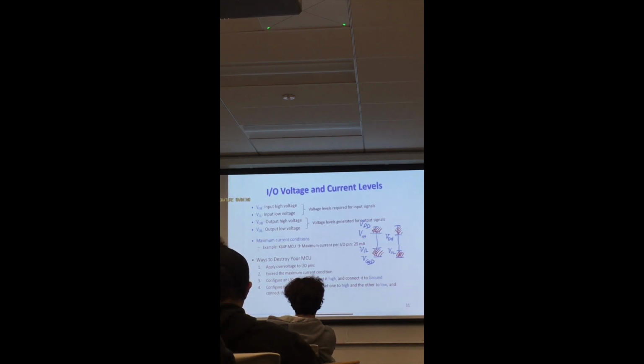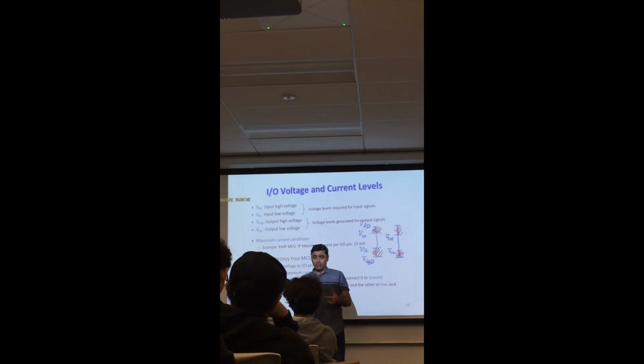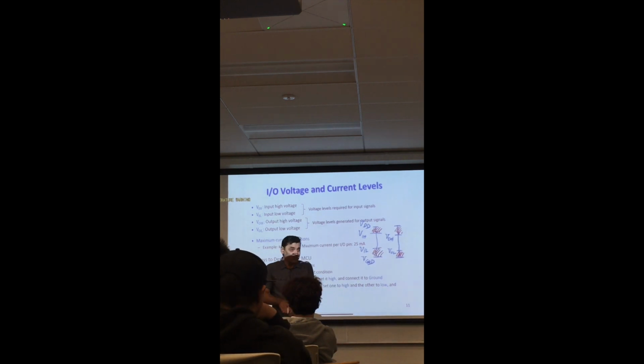Now, when you match different logic levels, our microcontrollers use the 3.3 volt CMOS logic family. These days we have gazillions of logic families: 1.2 volt, 0.8 volt. You may have a component, so make sure that you check the component and its specification, what this component will interpret as 0 and 1, which voltages.